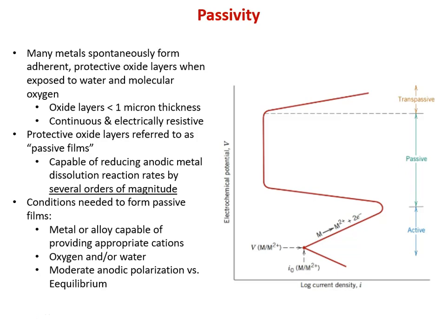Eventually, for most systems, we'll reach a point where if we apply enough potential, we will overcome that passivity and then dramatically increase the rate of corrosion, and that's called the transpassive region. But that's fairly difficult to do, and it typically involves the presence of some extremely oxidizing species that you don't normally encounter. So for most practical applications, we can maintain passivity in definitely typical atmospheric outdoor conditions, seawater, weathering conditions out of doors. So that's a potent weapon when we're trying to reduce our corrosion current: introduce a material that can form a passive film.